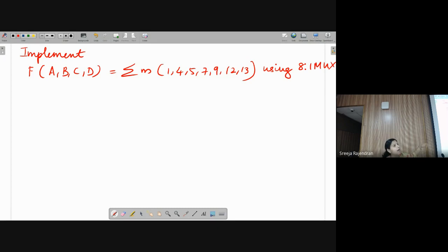Next we have the carry look ahead adder, where we have generate and propagate, so that the carry is generated in advance and I can speed up the process. Then you have the carry save adder, where sum and carry are computed separately. Each adder needs to have a name. All of them are full adders, adding 3 bits at a time, so a name is given separately to each of them.